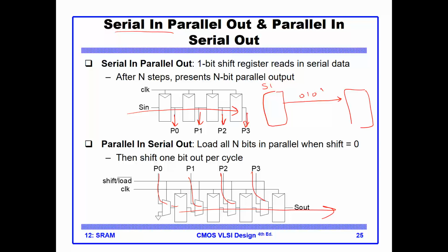So to do that, our words here need to be serialized, and this is exactly the circuit that we use. Sorry, that's not the one we want; we use this one to serialize. We load the parallel data here and then we shift it out, so we serialize it.